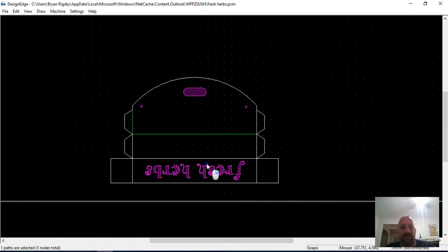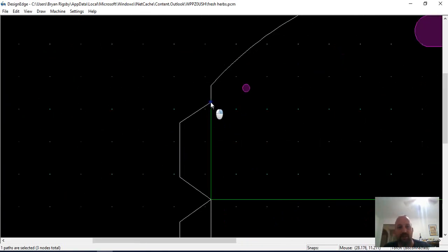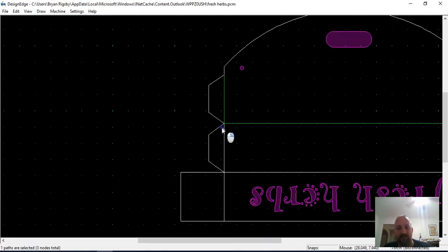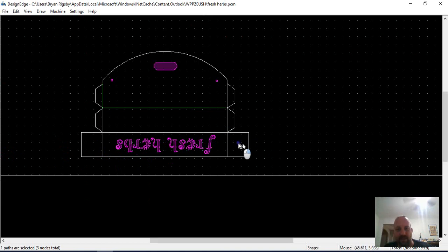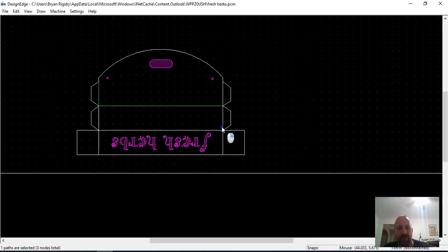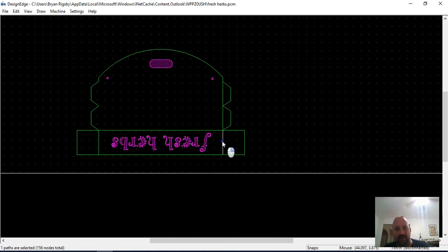Now the problem you have is when you try to join this outside piece, if you look, there are these middle lines or bend lines that are joined in, and those need to not be there. Your bend lines all come from the node points of this perimeter. So there's nothing that we can't find. We don't have a bend out here in the middle somewhere that we can't find. So I'm going to delete your bend lines out. The white ones aren't attached. These green ones are all attached. And so I'm going to use the X tool to trim those out.